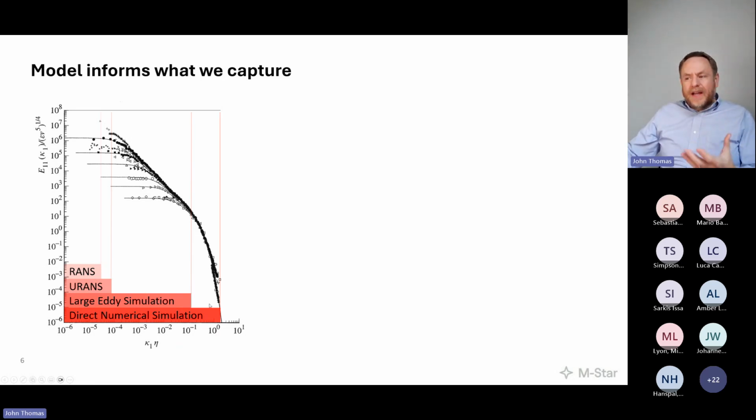So in large eddy, we want to be as close to DNS as possible while making it tractable from a simulation standpoint. But we certainly want to be within this Taylor scale. So we're poking into the dissipation range, where that filter is designed to operate most effectively.